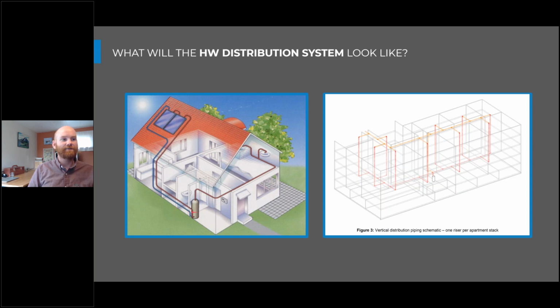It's connected to a storage tank and a pretty short section of distribution piping. Even if this piping was circulated, we're not going to see a substantial temperature maintenance load in that arrangement, just because we don't have that much piping in the building, and it's probably going to be 1/2 inch or maybe 3/4 inch piping.